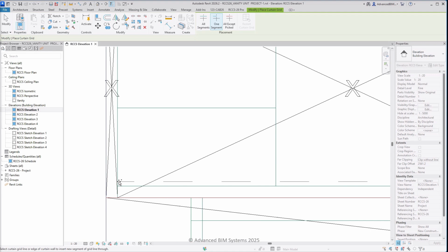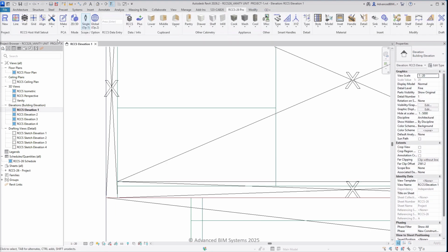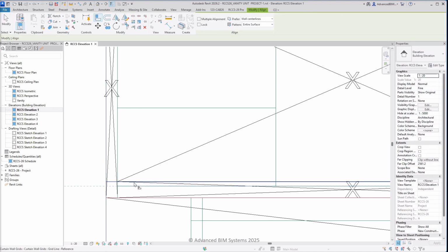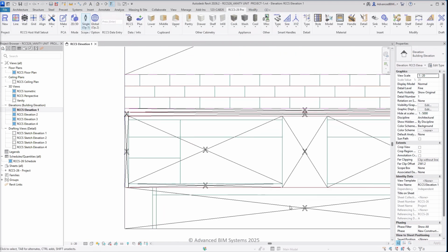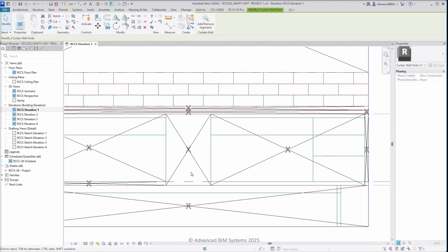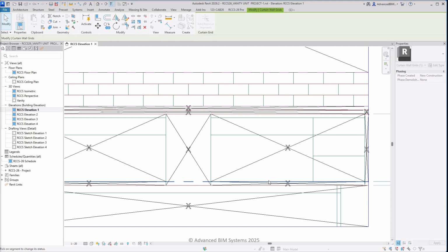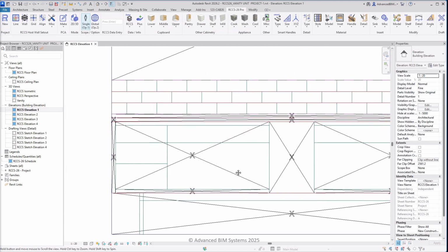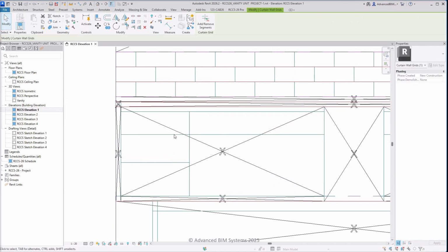It may be necessary at times to place a grid away from its 2D reference line, and then use the Align tool to correctly locate the grid. For grids that can host multiple grid segments, use the Add Remove Segments function to inset additional grid segments where required.